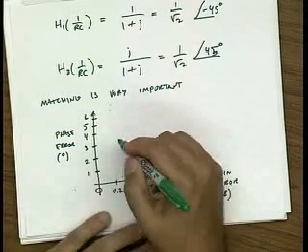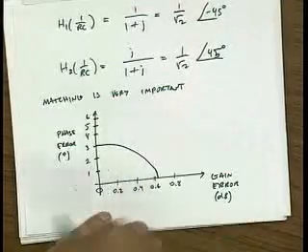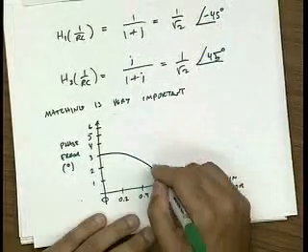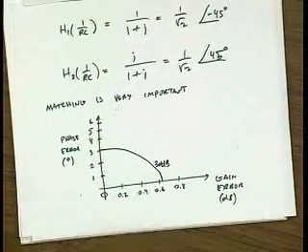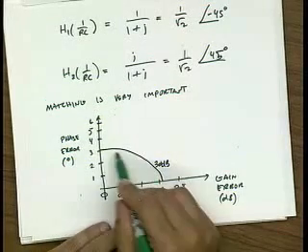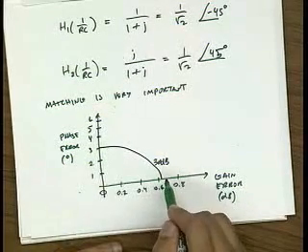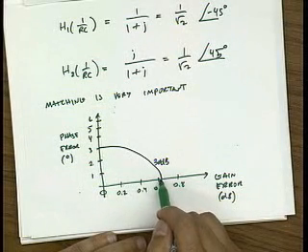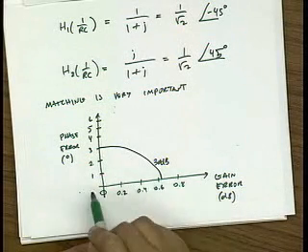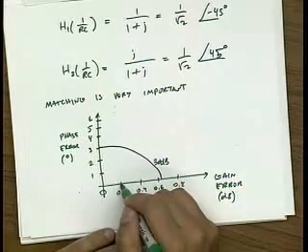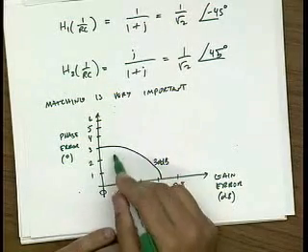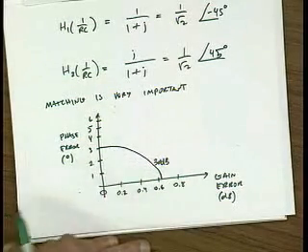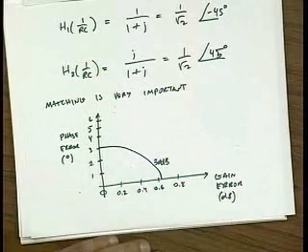So just roughly, you'll find that if you want 30 dB of image rejection, you have to basically lie somewhere on this contour. So if you have up to 0.6 dB of gain error, you cannot tolerate any phase error. But let's say you have 0.2 dB of gain error, you might be able to tolerate as much as 3 degrees of phase error and still get 30 dB of image rejection.